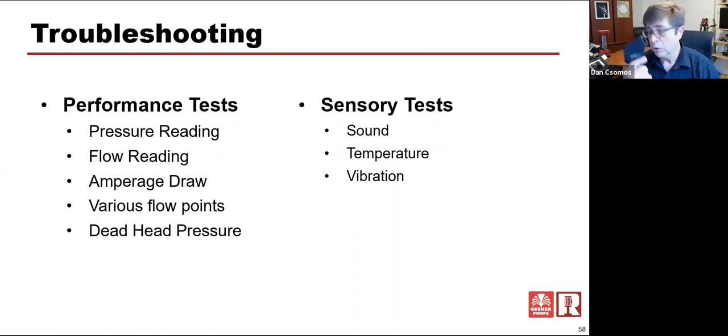And sometimes you can pick it up with one of these or one of these to be able to tell where, if it's got a bad electrical connection, there's going to be more resistance there, there's going to be more heat there. You'll be able to tell with one of these things if maybe you got a bad electrical connection. There may not be anything wrong with the pump. It may just be a bad wire connection inside the circuit box.